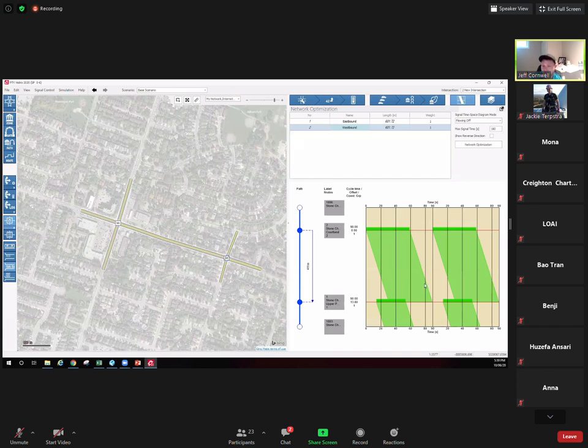And then you can adjust your offsets here. So in my example here, the coordinated directions are eastbound and westbound. So if you're looking at this time space diagram, this would be Stone Church at Cortland traveling to Stone Church at Upper Paradise. So by moving this offset, so I need to change this one here. I can change a few different things.